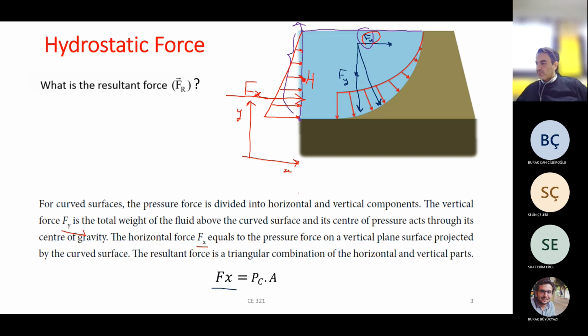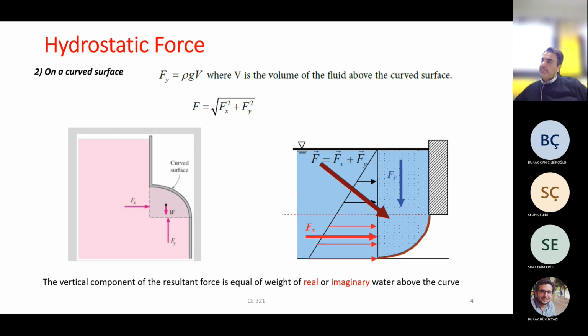Yeah, this is Fx. And how about Fy, the vertical force, the y component of F? For the vertical component, the resultant force equals the weight of real or imaginary water above the curve.